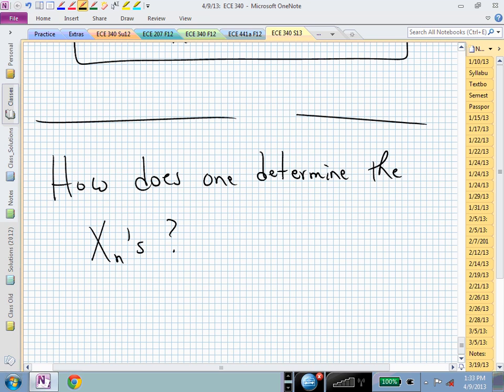Yes, so we would multiply both sides of our definition by cosine of 1 omega naught t. And then we would integrate all of the terms, and things would start canceling, wouldn't they? Because we would have sines and cosine products. And unless that was a cosine squared, everything would go away, because we would be integrating an integer number of sines and cosines over a fundamental interval of time.